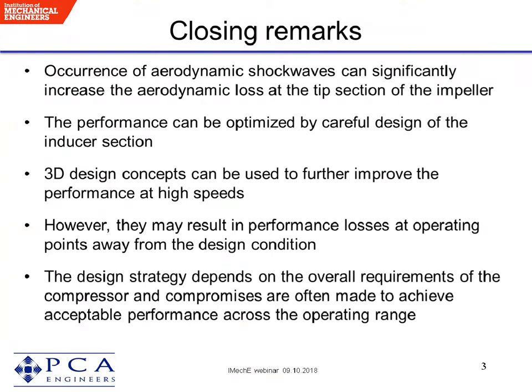Hamid, may I add something to that? Of course. I know of lots of studies where people have tried to improve the performance of diffusers by having freeform designs of the inlet, such that the inlet angle of the diffuser is adapted to the outlet flow angle of the impeller. Most of these have amazingly little effect.